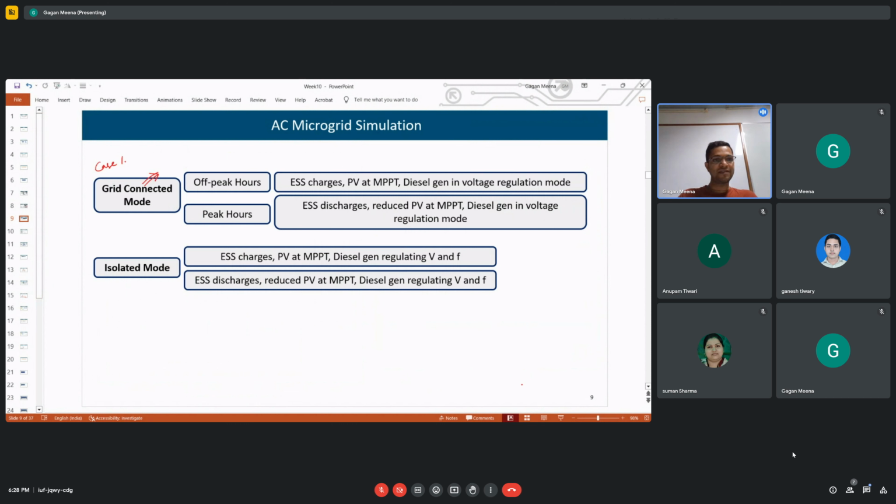So we have to design it carefully for reducing that. You have to tune it. The frequency of the filter has to be designed based upon our inverter, the required ripple that we want, and the current that we want to feed. All that will decide the frequency and the size of these inductors. We can use an L filter or an LCL filter. The advantage of using an LCL filter is that its attenuation rate is faster, it is more effective than an L filter. That is why it is being used here.